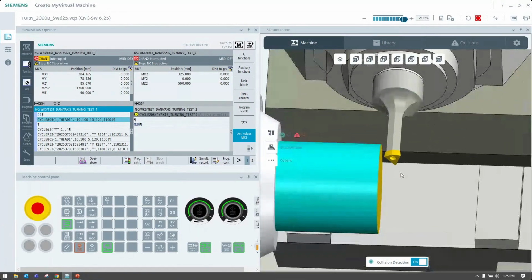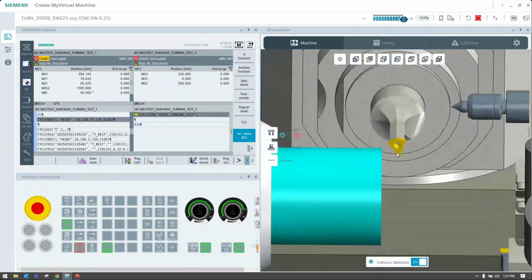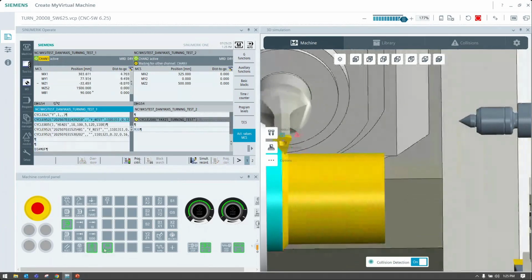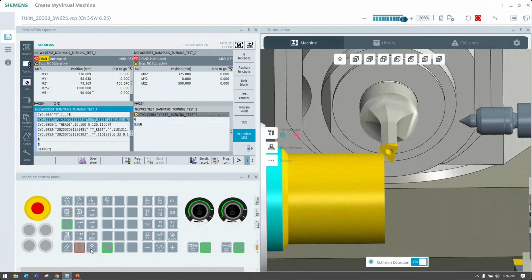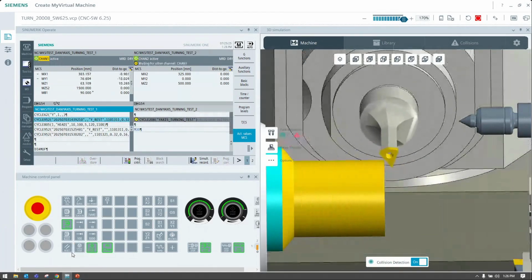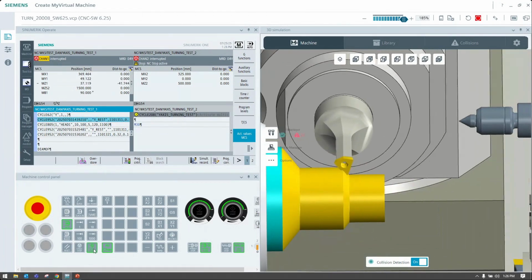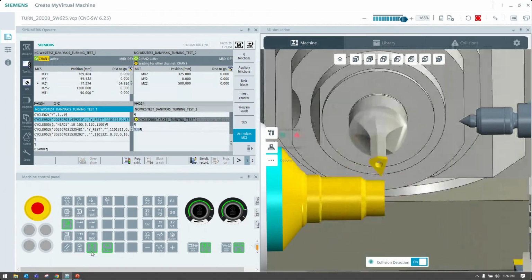And then I'm going to now reposition, and I'm going to change my insert. Now I'm changing to like 10 degrees, and now I can take a really heavy cut on that long side of that insert and really do some stock removal, right? Boom, big pass. Another big pass. So I can really start to get material out of my part relatively quickly. So I think this is where it's going to be really huge.